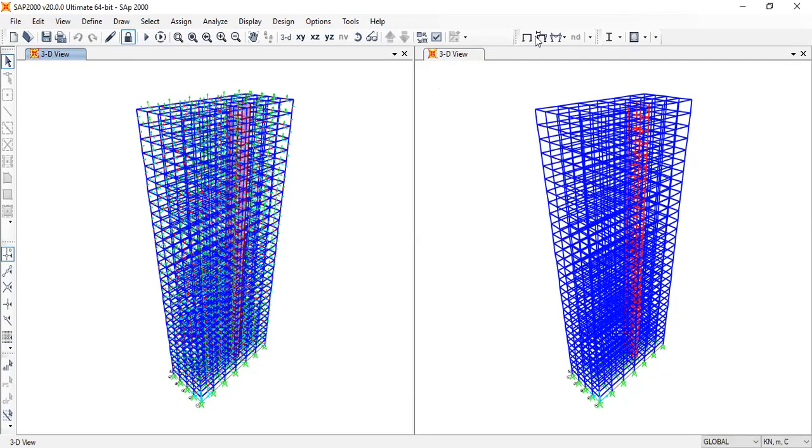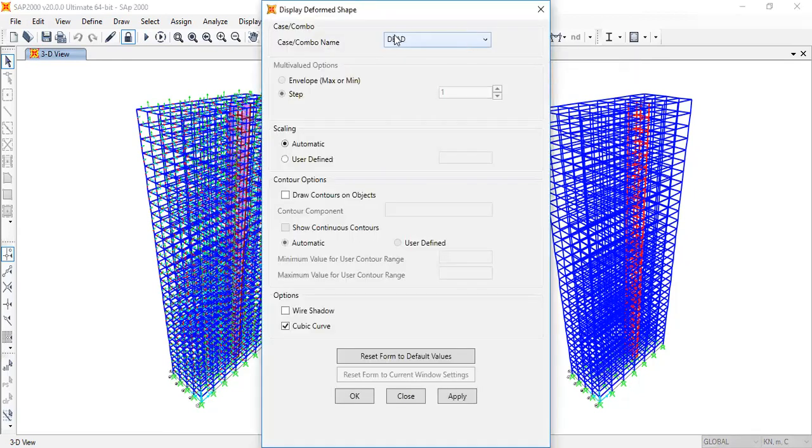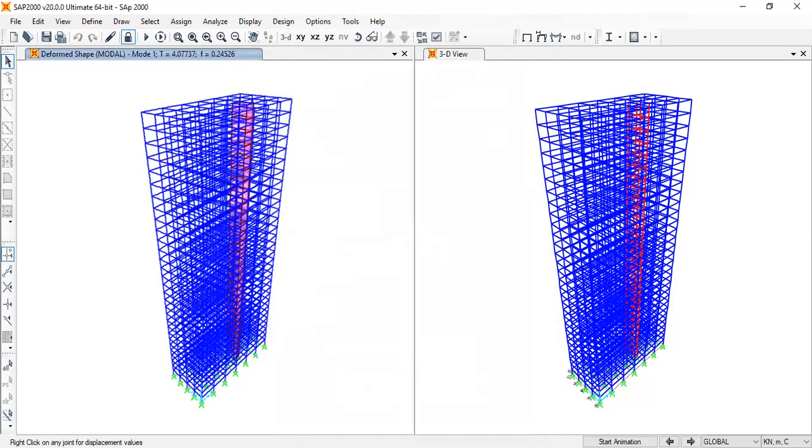So we saw the model case. You learned yesterday about the modal analysis of structures, right? Whatever the floors, however many floors they have, they can be idealized into lumped mass models, in which you can analyze how many modes and their periods, and the same thing is done here. If you go to the deformations, you can run modal analysis, and this will show you mode 1. The period T is around 4.0.